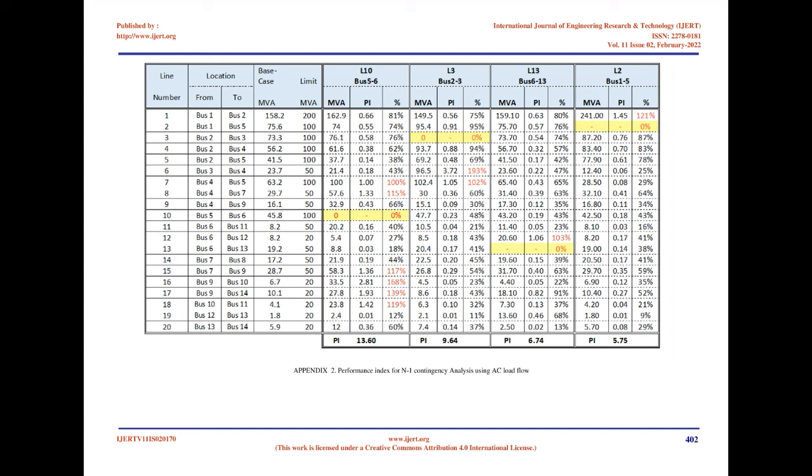Finally, for bus 6, a line 1 outage will reduce the voltage tolerance to less than 14% and increase the reactive power injection to keep the system under stable condition with very little dQ/dV equals 1%. Figure 13. QV curves for bus 6 and the highest PI contingency.